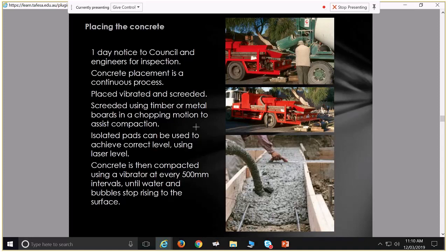I was just sort of mentioning the slump changes over the time of the pour. If you know what you're doing, technically you should be able to get that ratio right. But the longer it takes, the worse that ratio is going to get anyway. It's going to dry out. So they kind of need to add water to it, otherwise they're not going to get the whole job done before it dries out. Unless they're perfect, because there's also travel time for the truck as well.